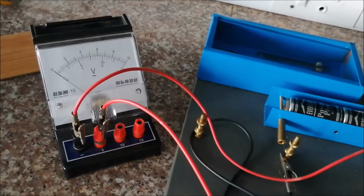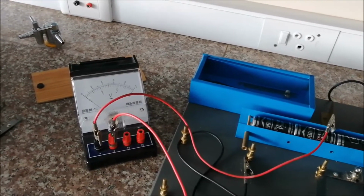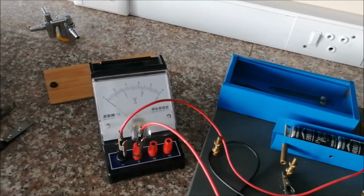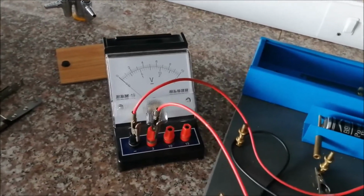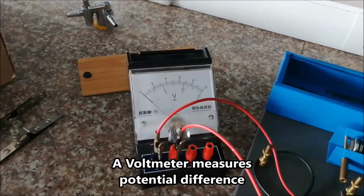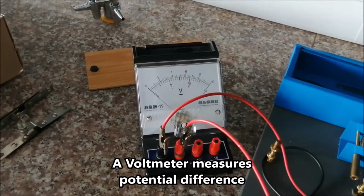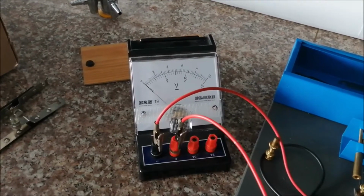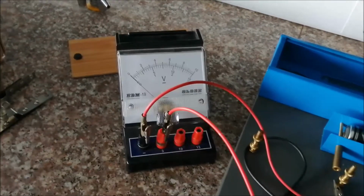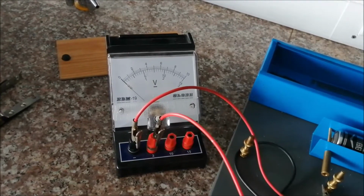We've had a look at our ammeter readings and how current flow affects the ammeter. Now we're going to add the voltmeter. Remember that a voltmeter always has to be connected in parallel. A voltmeter has very, very high resistance, so it doesn't form part of the electrical circuit when you connect it up. It just measures the potential difference between 2 points. Going back to our water analogy, that's like measuring the difference in height between 2 points on the side of a hill that has a river flowing down it. You're measuring the difference in altitude, which gives you an indication of how fast the water is likely to flow down the hillside.